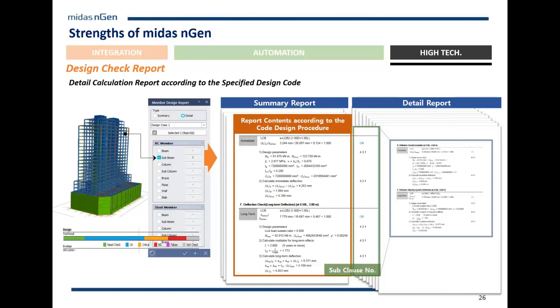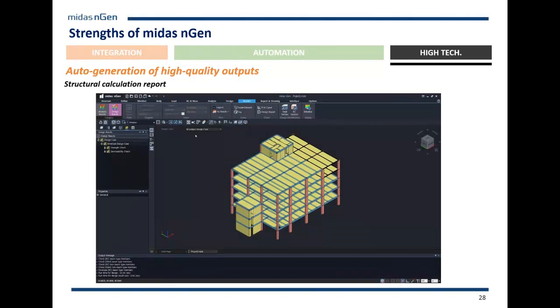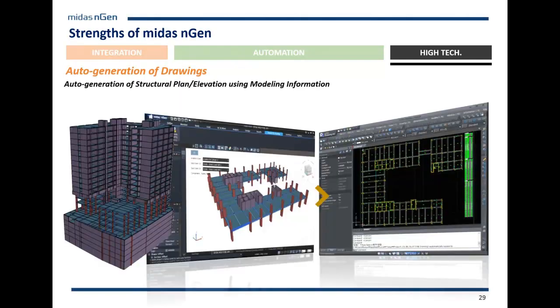And they have got codal provisions with subclause numbers as well. Then further we can use report maker to generate the information about our model file, our project. And this is going to show the same thing. So let's move ahead. Drawings. So drawings can also be generated by the program. We just saw how easily the structural plans and the reinforcement arrangements were done by the drawing software.